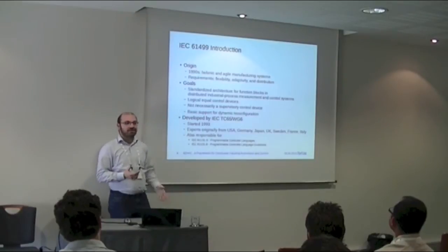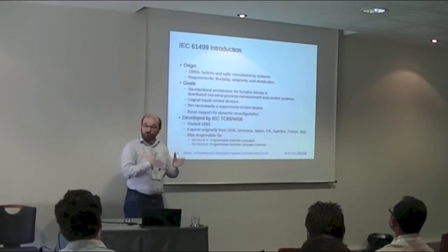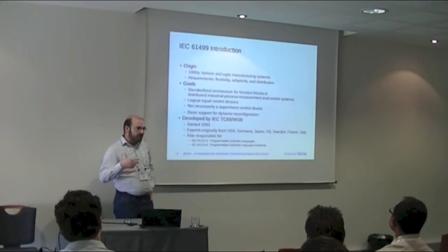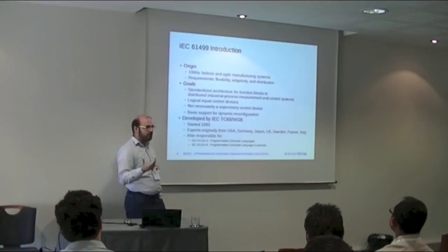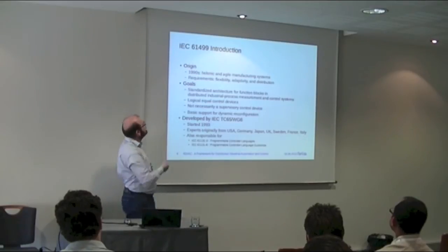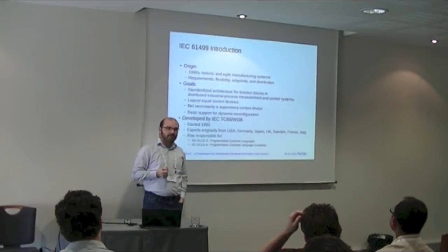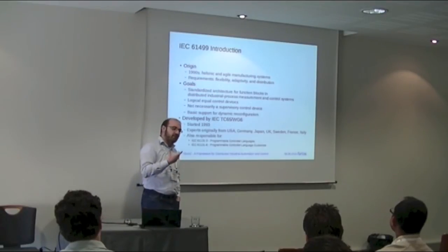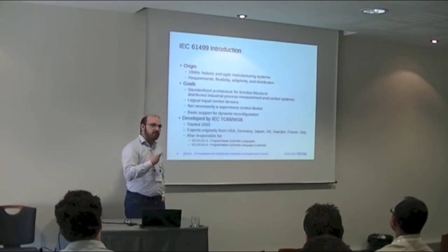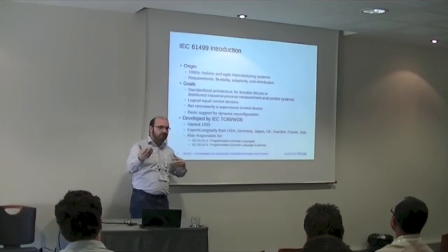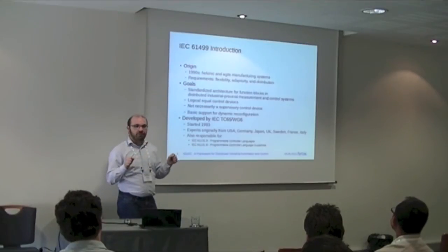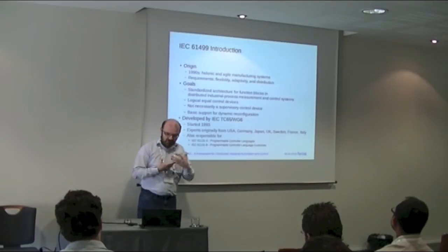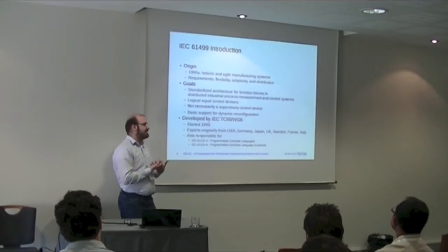And from that it already originates that PLC programming as we know it, and as it's still used, which hasn't changed much, is not capable of fulfilling all these requirements. And therefore, a new paradigm has been developed. It has been developed for more than 15 years. The first version of the IEC 61499 standard was presented in 2005, and it tries to improve the then-existing way of programming PLCs in order to be more distributed, so that we can have distributed control devices that each interact with their part of the machine, negotiating with each other, so that we have adaptability and reconfigurability already designed into the programming language.